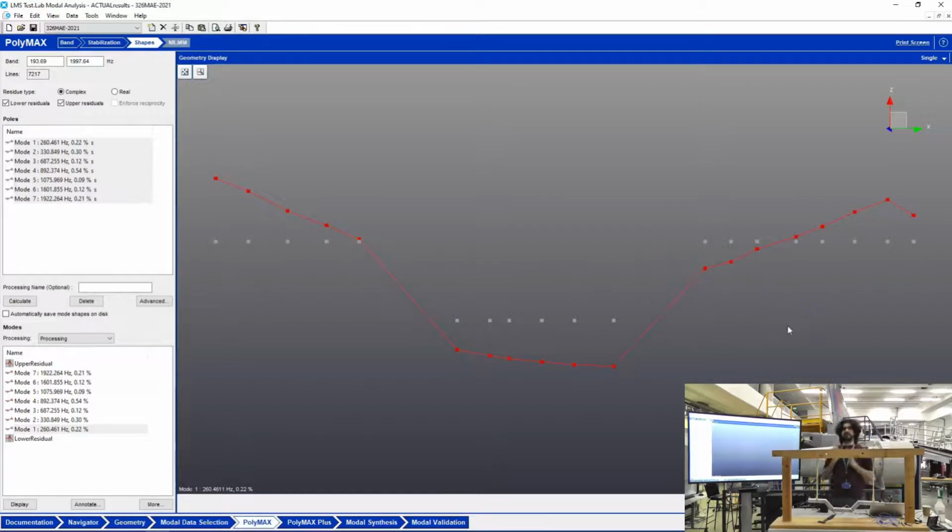Now you don't need the animation because this is the mode shape. Remember I told you the mode shape is a vector of numbers? Well, each number corresponds to an amplitude. This vector is 19 numbers long, and each number is how much the corresponding node has displaced. Number 1 is how much node 1 has displaced, node 2 is how much node 2 has displaced, and so on. See, for node 5 we almost have 0 as amplitude of displacement, and these ones as well.